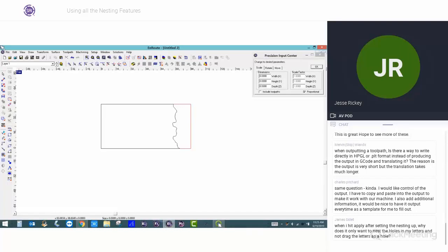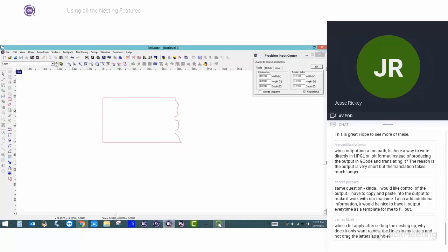So what we would have to do is select our shape, and then inside here it says create plate from selected contour. We could also go from machining and plate from contour. What that does is automatically create the plate as that oddball shape, and now we can nest parts back into here if we choose to.